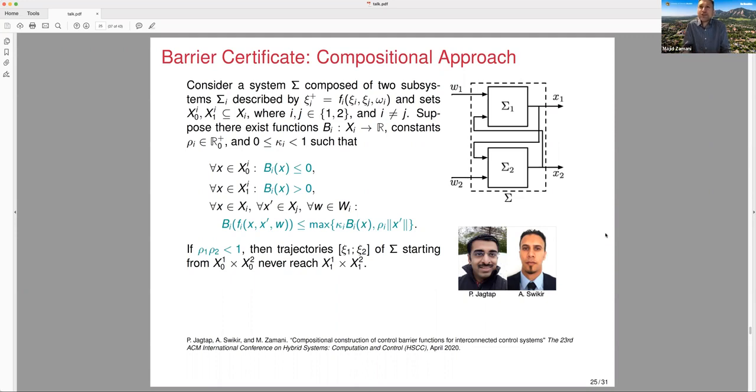But there is a trick here. The fitting should be exact because we don't want to lose the formal guarantee of the controller when we apply the classifier. We have a very interesting example of a gigantic lookup table that boils down to a decision tree of like 5 or 6 states for an inverted pendulum example. What we care about is ensuring that the formal guarantee of the controller is preserved when we do this classification in order to reduce the size of the controller.